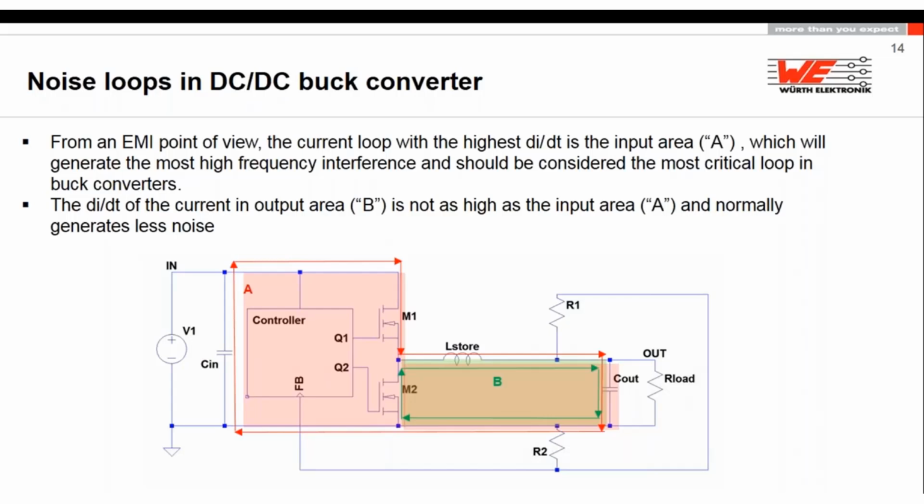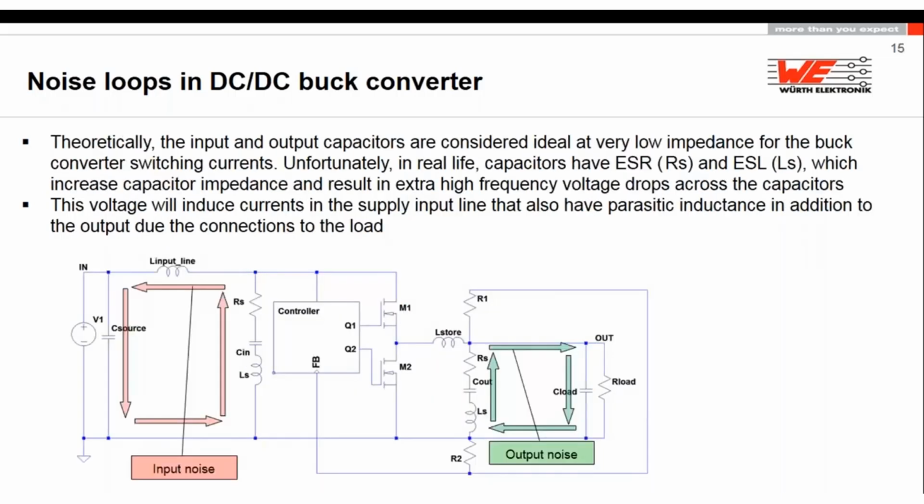So you have to think about it: in the buck converter, you have a quite noisy input area. This is what you have to filter. In a boost converter, you have to filter the output more. The boost converter is not so aggressive on the input, but is very aggressive, very noisy on the output path. So these are the two areas where you have to think about this.